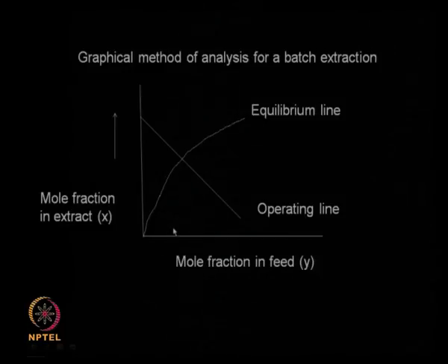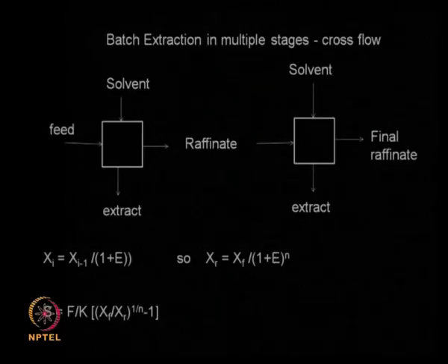So just like in adsorption, we will see where the equilibrium line intersects with the operating line, and that particular point will be the concentration of the solute in the solvent layer that is leaving the liquid extractor.